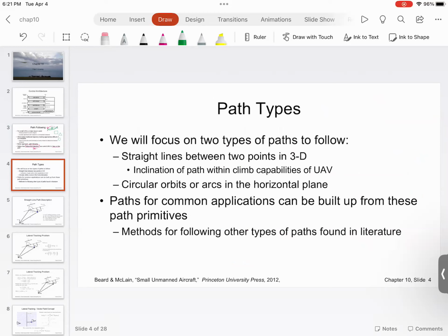Now, at the end of the day, there are different techniques and different algorithms. As you go more and more into the studies and details, path planning is an entire course, actually an entire field in itself. There are different techniques. Some are analytical, some are geometric, some are statistical. But we are going to look at a very simple technique: we are going to construct the path using a straight line segment and an arc. A straight line and arc.